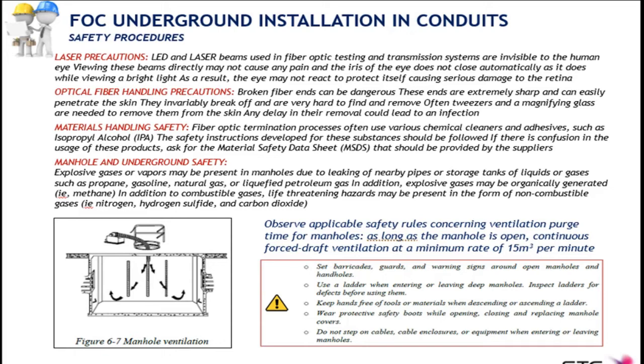Another hazard you have to pay attention to is the fiber handling as such. You know that the fiber optics, the fiber core inside are very brittle, and the small tiny pieces of fiber that are extremely sharp can easily penetrate the skin. So they are transparent and very difficult to find once they are in your skin.